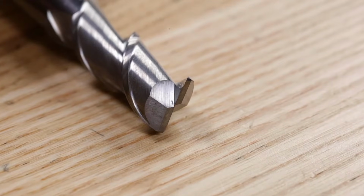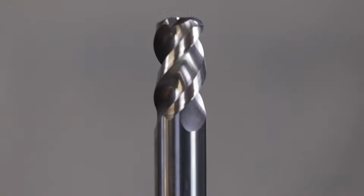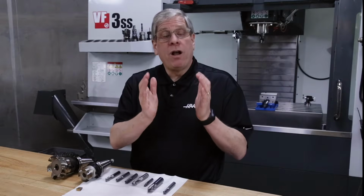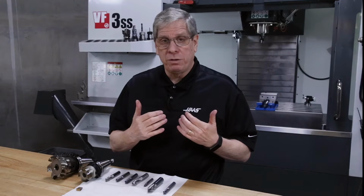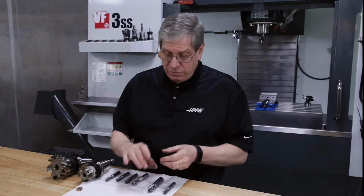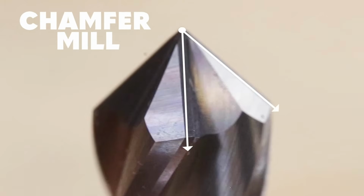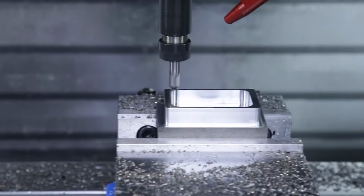End mills come in different configurations. They can be square end with sharp corners or have radii on the corners like this one. They can even have a 45-degree chamfer on those sharp edges to keep them from chipping when cutting tougher materials. Now, that's not to be confused with a chamfer mill, which also has an angle, usually 45 degrees, but on the whole end and not just on the corners. These cutters are used to produce chamfers to break sharp edges on corners after milling.